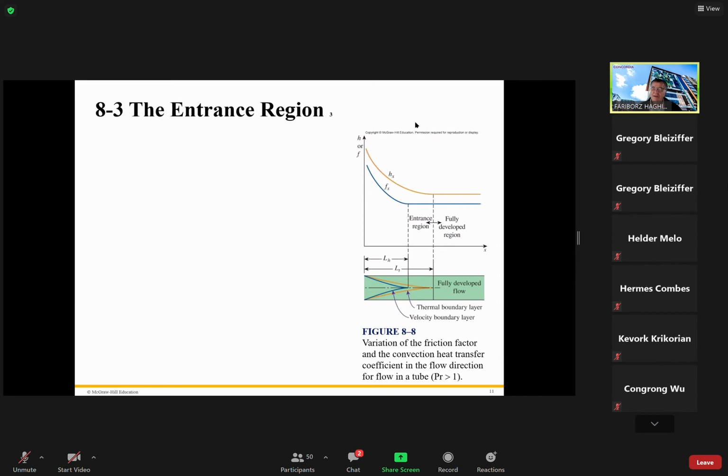And the whole idea it's trying to say here is, even for laminar or turbulent flow, the heat transfer coefficient at the entrance is almost infinite, slowly decreases, and when we become fully developed, remains constant. It means from here all the way to the end, the heat transfer coefficient will not change. That's the meaning of it. Let me go term by term.